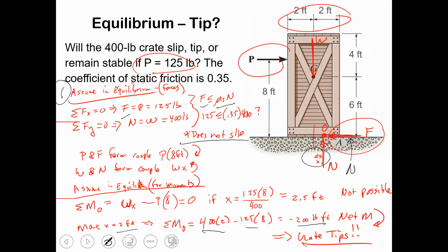Or maybe it actually satisfies force equilibrium, like, so for this refrigerator, we have this force equilibrium equation. And we can show that it doesn't slip because the friction force is able to withstand that P, right? Because, and what's the maximum friction force can be? Ollie, what's the largest force that friction can get to? Nope. Isaac, what's the largest force that friction can get to? Matthew? Largest possible force? Yeah, there's this thing called the coefficient of static friction times the normal force, right?